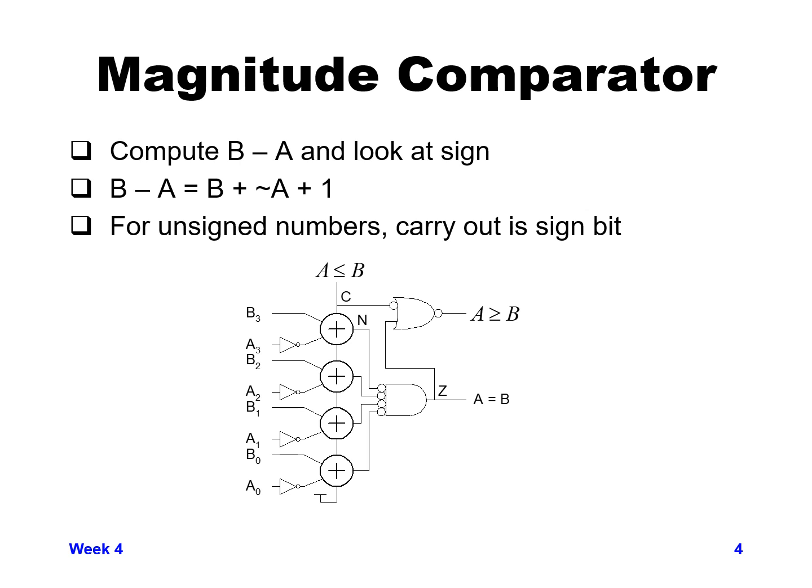If it's still positive, then B is greater than A. So one thing we can note when we're dealing with digital numbers, ones and zeros, and we have n bits, is that in order to calculate B minus A, that value is equal to B plus the inverse of each A bit. So if we take not A bitwise and add it to B and then add 1, we wind up with the same value as B minus A.